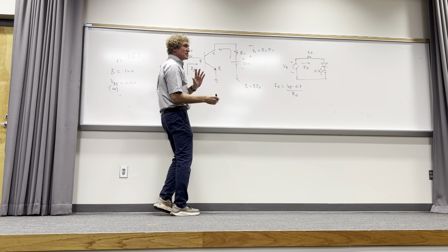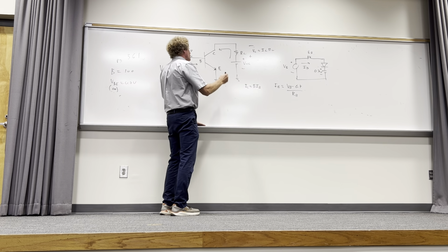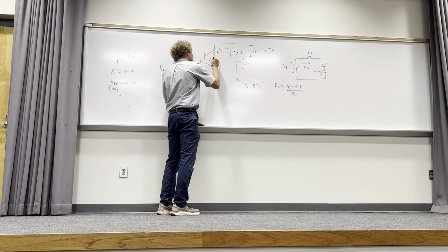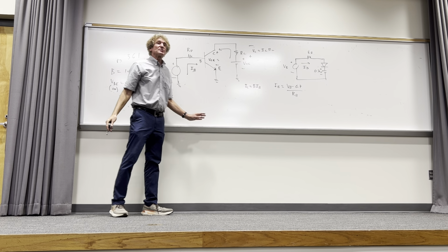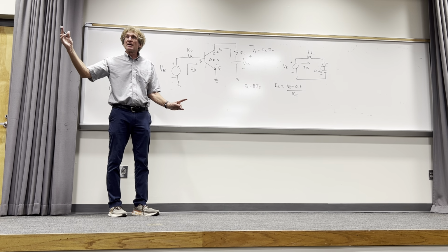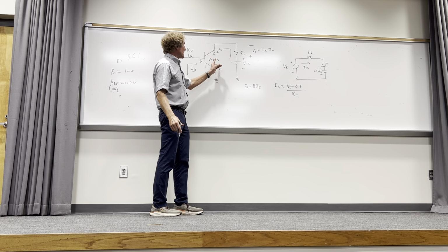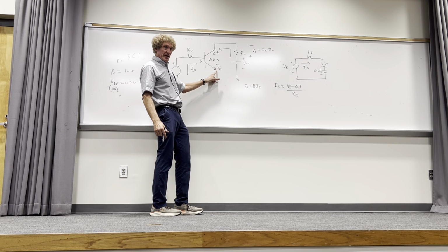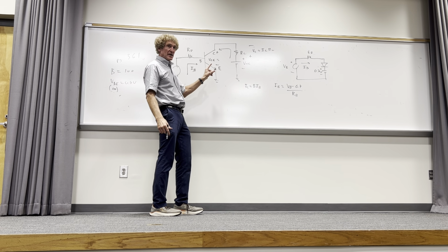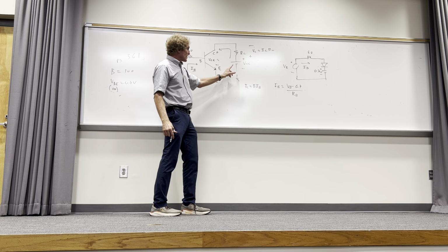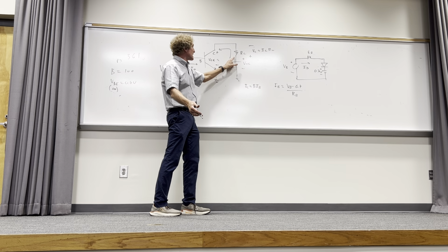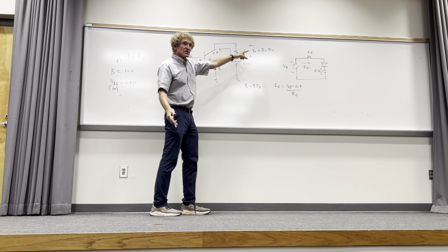All right, you with me on this? So the question that they would like answered is, what is the voltage between here and here? Just tell me what this VCE is and why. I bet you know. Listen, if I want the voltage from here to here, start at this terminal, right? We start here, that's where the negative is, on this plus to or minus to plus, right? Go around, I get an increase of VCC, and then I get a voltage drop of that small c, or IC times RC.